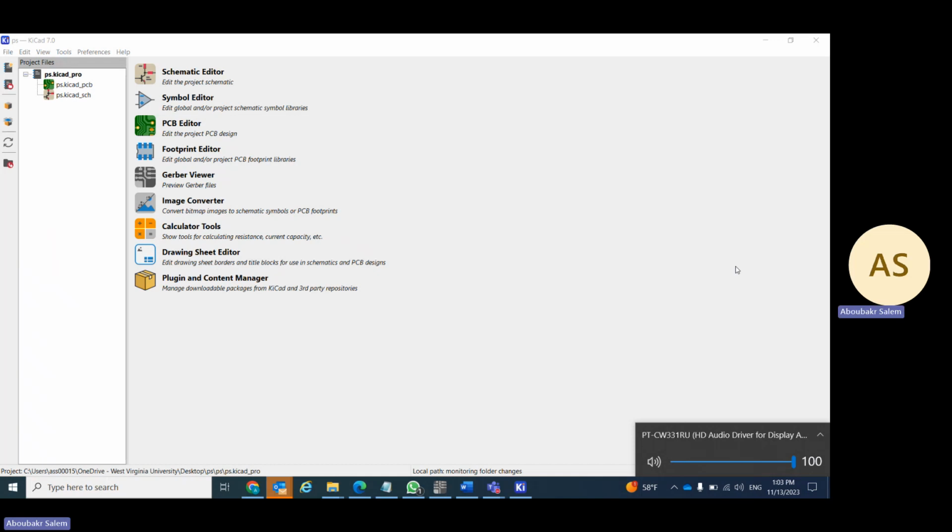But we still need transformer, correct? Transformer to step down the volt from 110, for instance, to, let's say, 6 volt. Okay, so 6 volt, I believe this is the lowest volt you may find in transformers. I'm not sure if you can find less or not, but 6 volt is enough to have +5 DC supply or not.